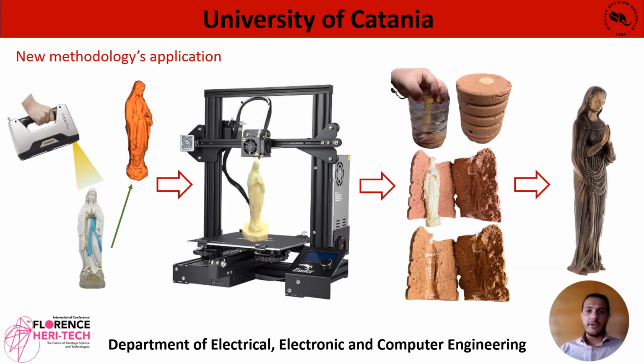The first stage of the new methodology is the 3D scanning of the prototype, and then proceeding with the 3D printing in PVA. It was decided to use this material, which is normally used as a support material for classic 3D printing, because it has the property of being entirely dissolved in water and therefore biodegradable. In this way, compared to the traditional methodology, the phase of melting the wax inside the refractory material in the oven at high temperatures is omitted, and an environmentally sustainable methodology is used.